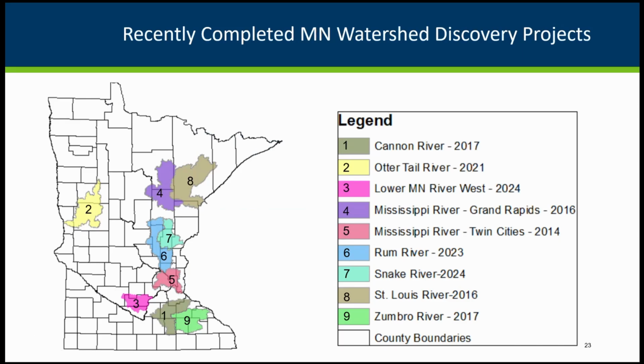So a process called discovery is usually the start of the risk map process. It focuses on partnering with other federal and state agencies, as well as local communities and non-governmental stakeholders to determine the mapping needs, generally on a watershed scale, but some are down on a countywide level. One key component to this process is data collection, particularly from local agencies and communities. The data collected is analyzed to help determine new study or mapping needs. Watersheds are generally prioritized if there's a large change in hydrology, development, or other factors, or if the counties have older maps or data or are unmapped.